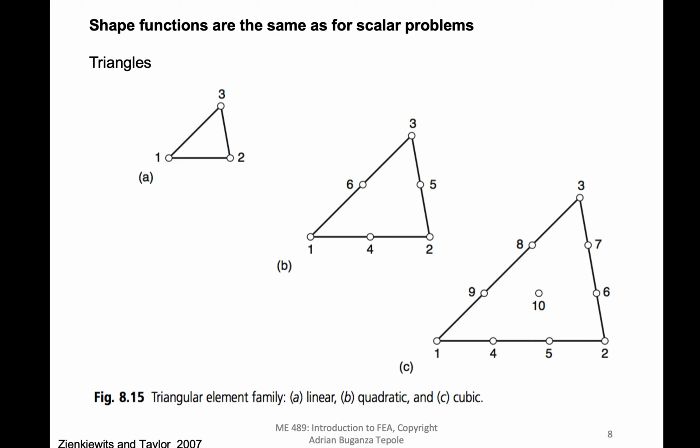The next thing is just to compare this a little bit with the heat transfer problem that we have talked about in the past. First thing to note is that for the heat transfer problem, we introduced shape functions for the triangular element and for the quadrilateral element, and the shape functions that are used for the linear elasticity problem are exactly the same. So the definition of the element and the shape functions, which are used to interpolate functions and derivatives, that remains the same.